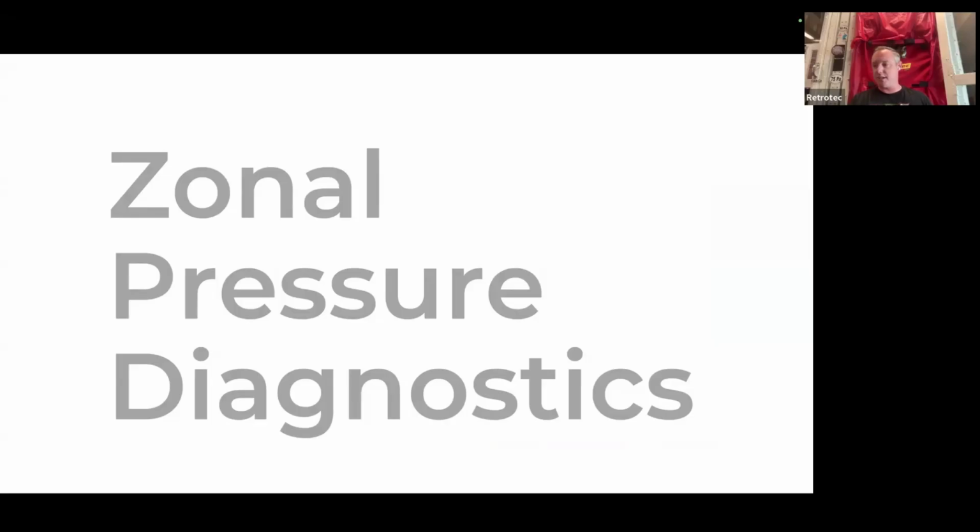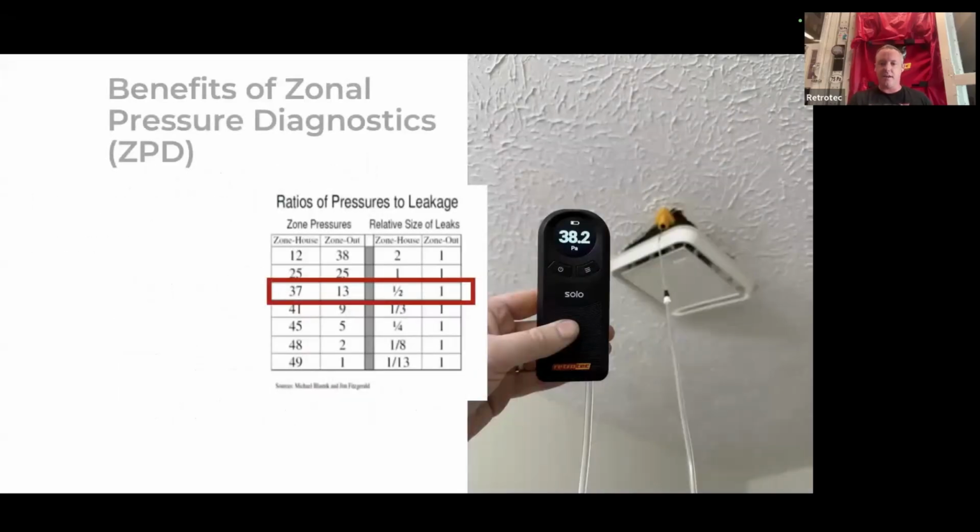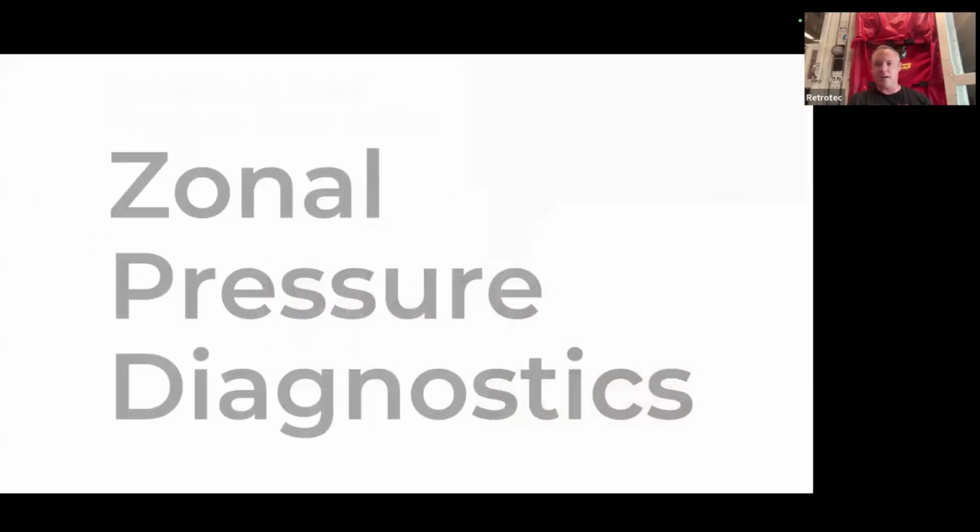We'll get into thermal imaging later, where you kind of have to plan around the weather. We'll talk about that in a bit. But if you plan to do thermal imaging or zonal pressure diagnostics, I usually like to keep some fog with me too, just in case I want to make those agree with each other, as a sanity check. It's nice to do sometimes. We'll jump into zonal pressure diagnostics, and then we'll stop and take some questions.